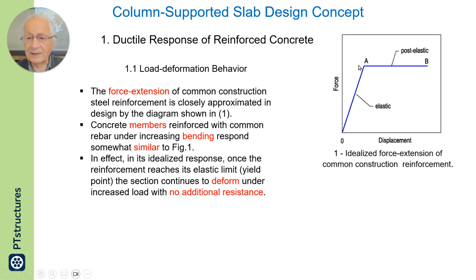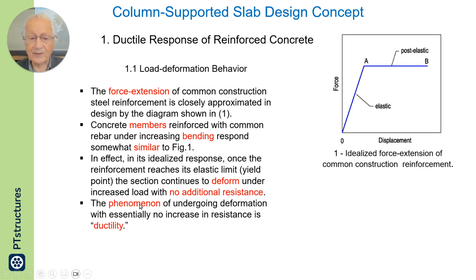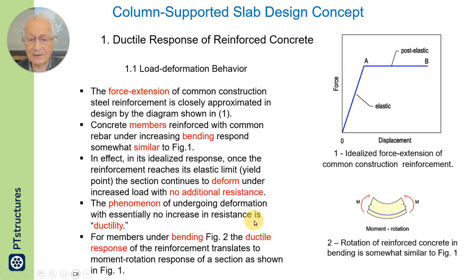The member can possibly take additional load, but the section reaches a plateau. The phenomenon of undergoing deformation with essentially no increase in bending resistance is ductility.